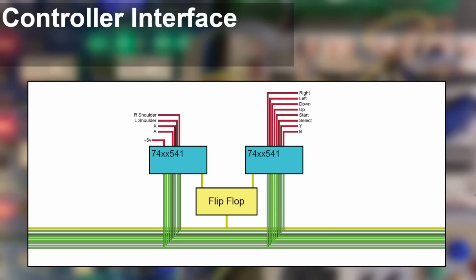Now clever viewers will immediately think, well, what if the right button is being held down on the control pad? But if I write my controller reader code such that if it ever sees that top bit not set, then we know that must be the low byte, and I can just discard an extra byte from the I/O port and recalibrate myself to the correct way round. And if someone's going to switch the CPU on and permanently hold the right button down, we probably don't have to worry about behaving perfectly in that circumstance. So let's have a go at building this.